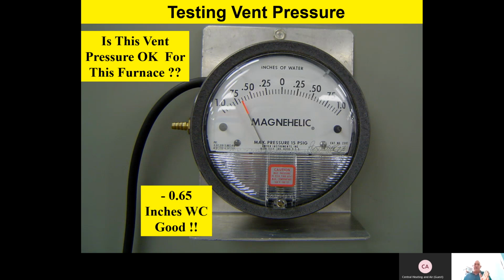So the vent pressure is a little bit lower here, where it's still giving us reliable operation, but we want to watch that, because if it's degraded from the last time we checked it, we need to make sure our vent pipe is clear and we don't have any critters that have built a nest in the vent pipe, or mud daubers that have got in there and obstructed it. You get the idea. So this is one of the reasons we recommend that every year we check our vent pressure to make sure that it hasn't changed or degraded from the previous year.